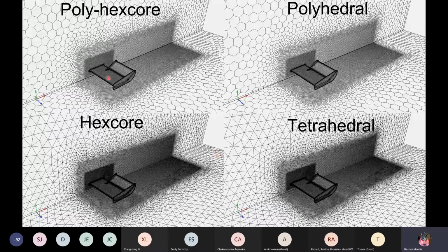You'll notice, around the wing, we've got a very fine mesh. We've got some flow structures that are going to be shedding from here. So again, around this region, we've got a local refinement, but then, far away from the actual model, it gets relatively coarse, right? Because there's not really much happening around that region. So again, what I did to start with is I started with no refinement. I just made sure I captured some of these features, and then you can progressively start to make the mesh finer and finer to understand how fine does it need to be. The reason I did this study was just to show you the different mesh types that are available and what the actual benefits can be.